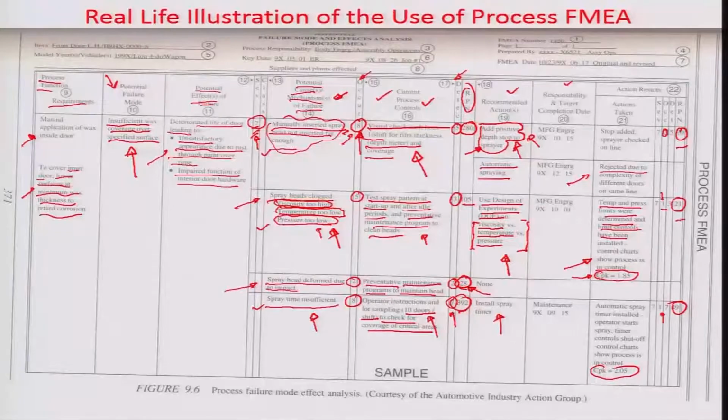So the reduction in RPN as recorded through these countermeasures is documented finally, so that 10 years down the line, if the same defect gets repeated, you can come back to this documentation, a one-sheet representation of the whole defect tree and the countermeasures, and see what went wrong so that the defect came up again. So this is a control which needs to be there for every process, every design aspect related to a product which goes through a manufacturing process, and it's a very useful tool to carry out good quality product synthesis.